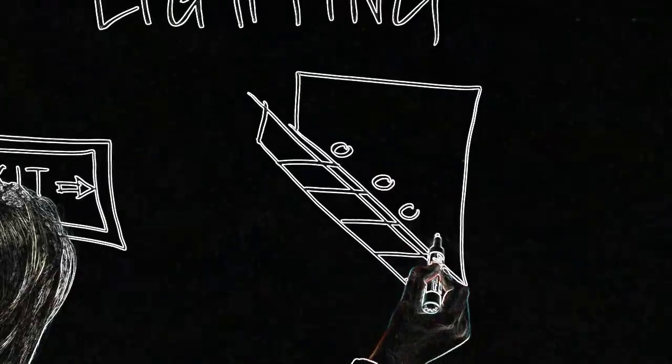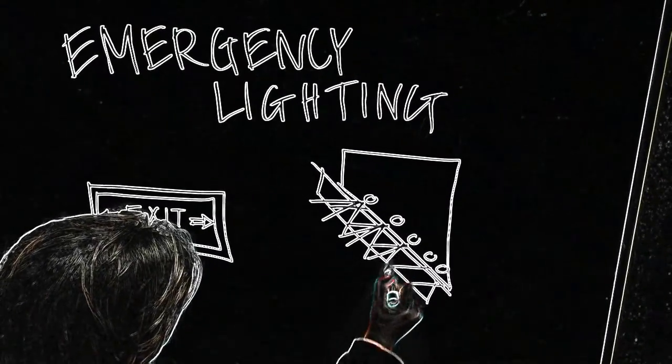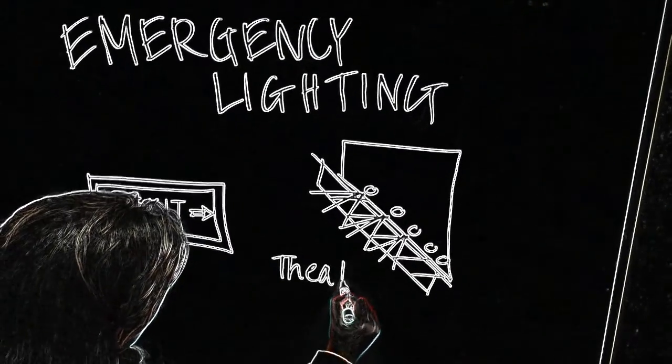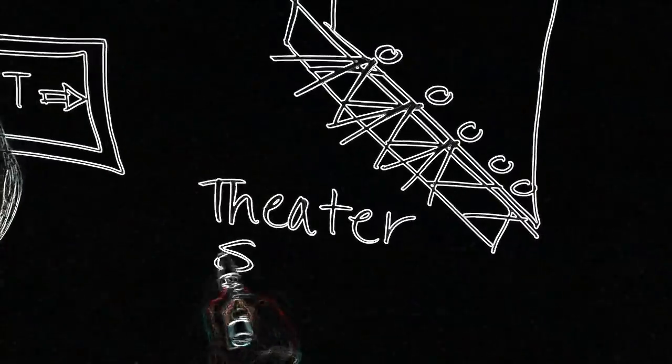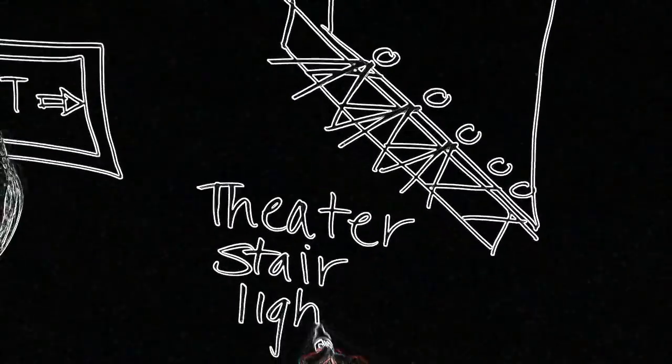Both general exit lighting and exit and area of refuge signs must be lit at all times when a building is in use. The codes specify minimum lighting illumination levels. Lower levels might be allowed for certain building types, such as theaters, concert halls, and auditoriums.